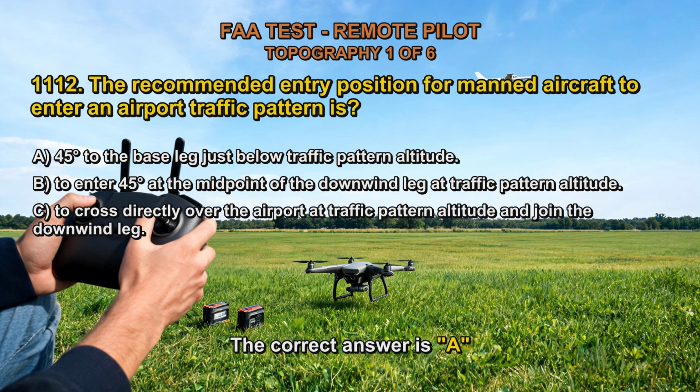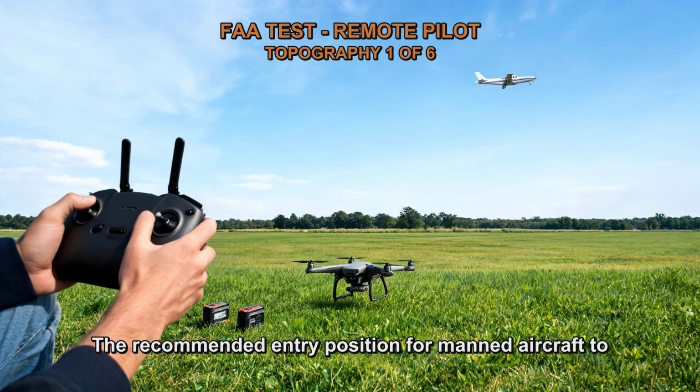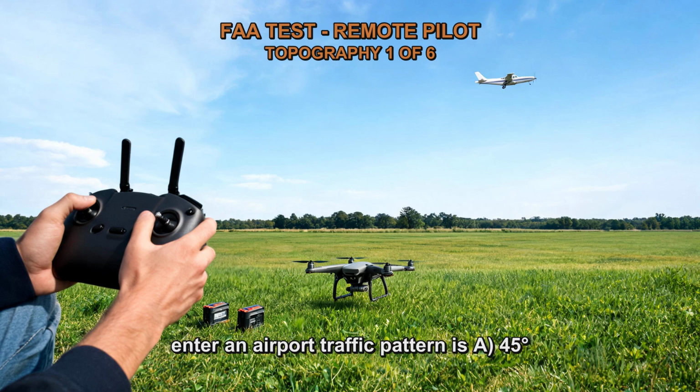The correct answer is A. The recommended entry position for manned aircraft to enter an airport traffic pattern is A. 45 degrees to the base leg, just below traffic pattern altitude.